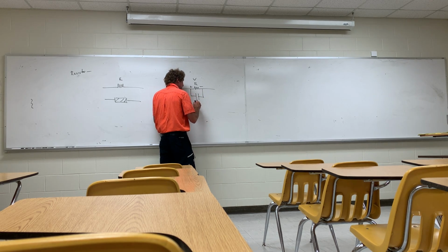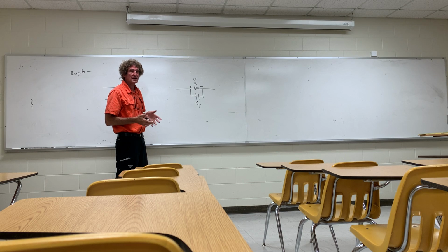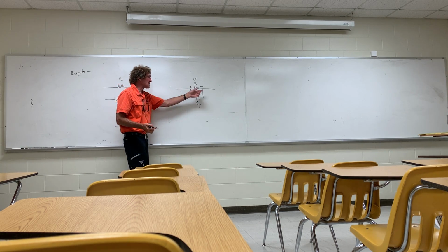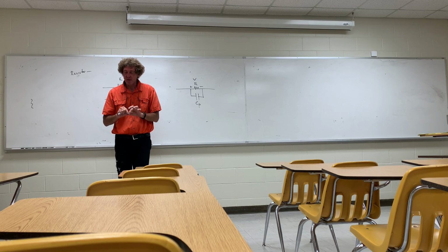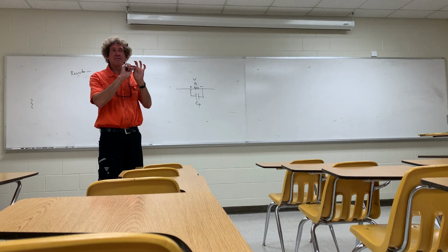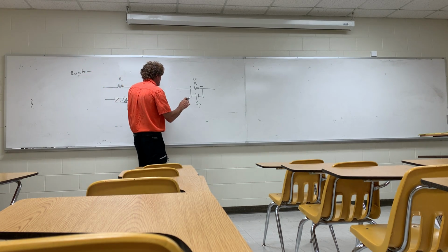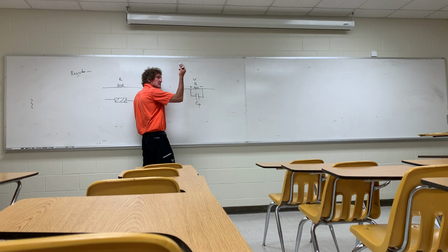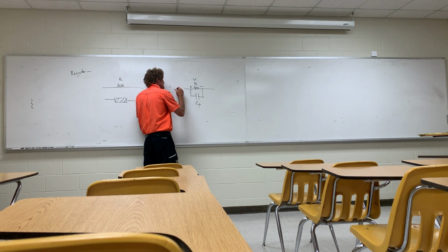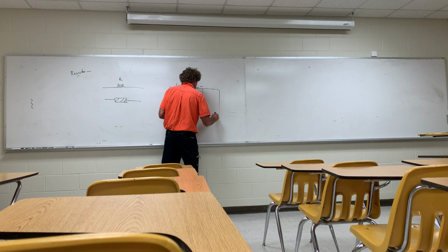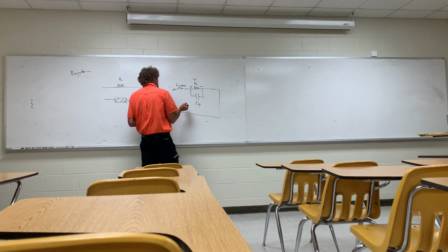So they model this by a capacitor. And they'll call it C sub P because it's parasitic. First of all, we don't want it there, but it's there. It's a parasite, you might say. So it's a parasitic capacitance. But we also have metal leads. They're made usually of copper. Anytime you have any length of lead, you have an inductance. You can't get rid of it. It's an internal inductance plus an external. So normally when they model this, they'll also put L, of the lead. And that would be the model for a resistor, right here. That's truly what it is.